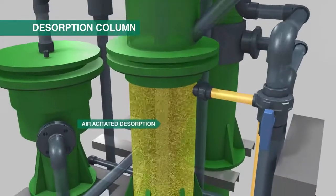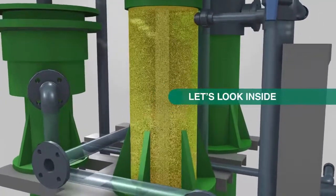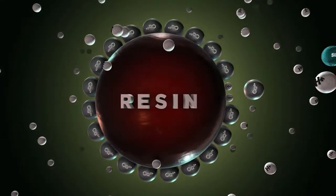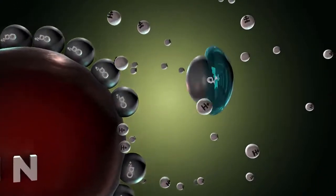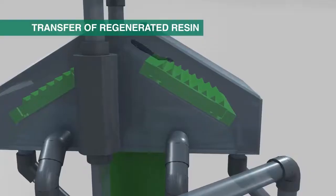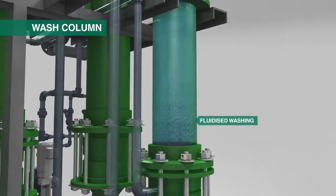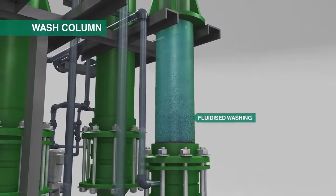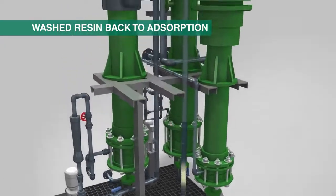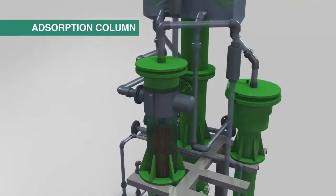This is done at very high concentrations, and as you can see, calcium is then removed from the resin bead, H+ is regenerated, and calcium sulfate is created as a byproduct, which is gypsum, which is obviously a valuable byproduct. The resin is then sent to a wash column just to wash off any residual acid, before being sent back to the top of the adsorption column via pneumatic airlifts to complete your cycle.